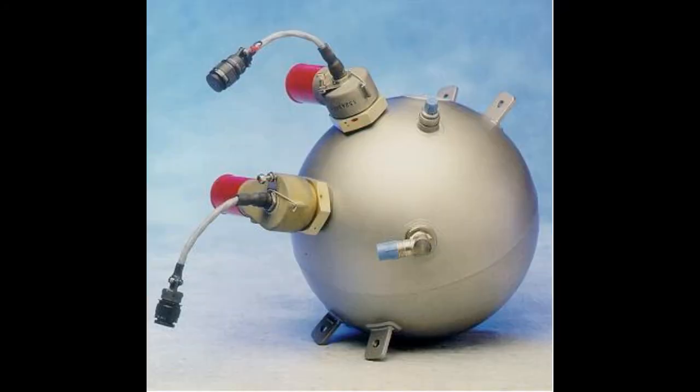When we do remove a squib from a bonnet assembly in an HRD bottle, we never use it in another bonnet assembly. Sometimes they can be specially sized to fit a certain container, and we don't want to risk a malfunction in our extinguishing system because we used an incorrect squib.